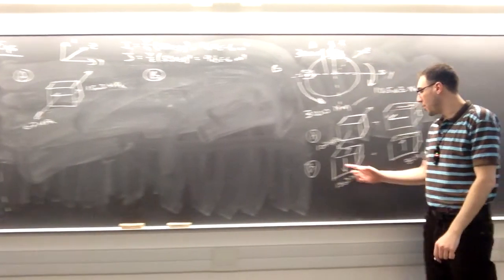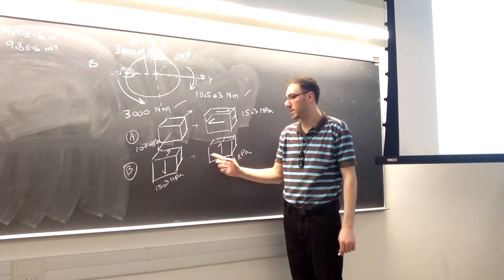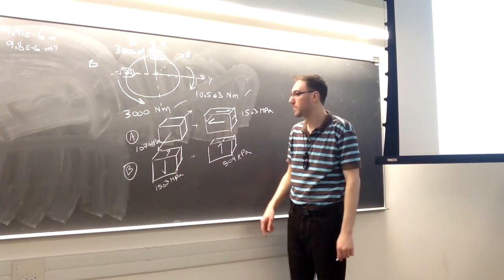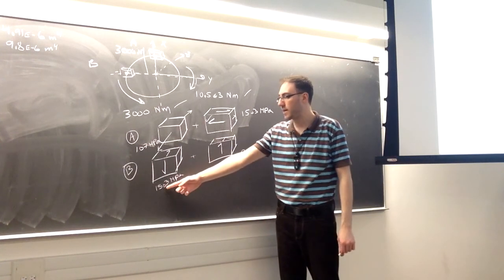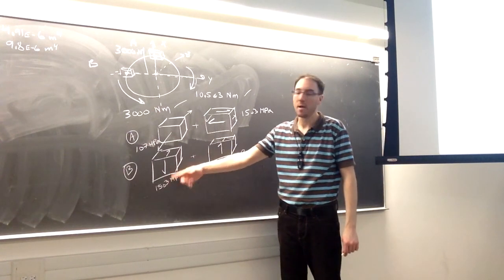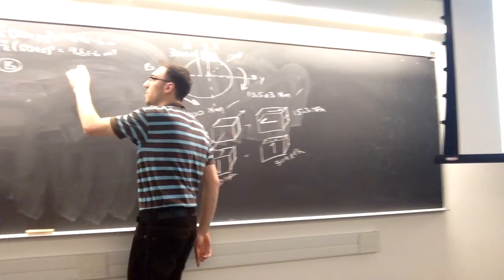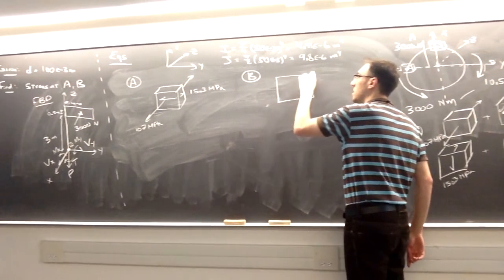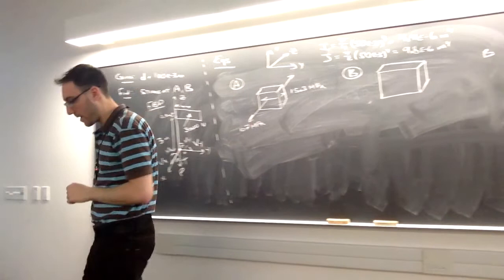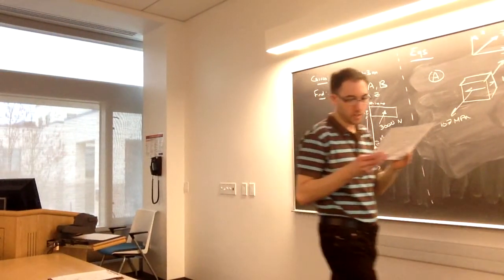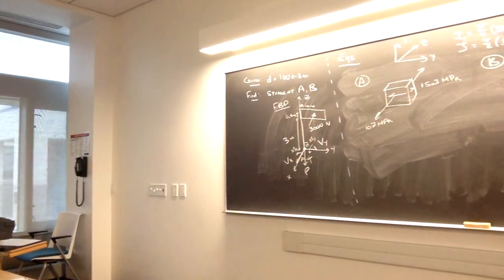At B, I have no normal stresses acting in this scenario, but I do have two shear stresses. They're in opposite directions. So because they're in opposite directions, I have to take their difference. So I need 15.3 megapascals minus the 509 kilopascals to get the total stress. So pointing down, I'm going to have 14.8 megapascals of shear stress.